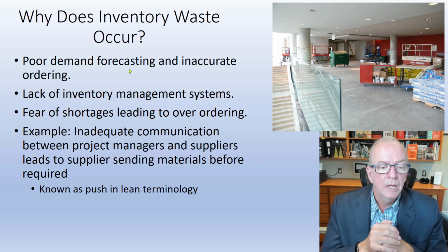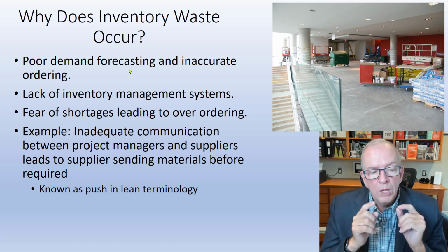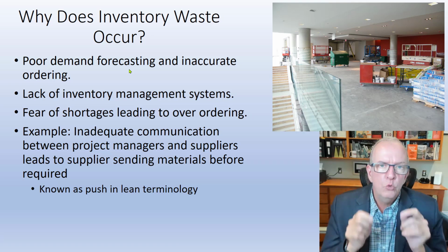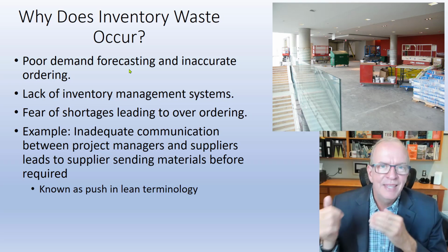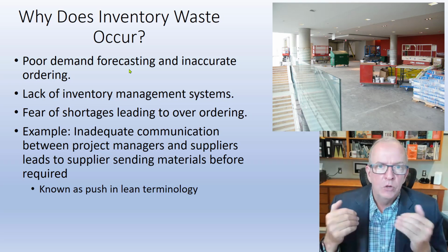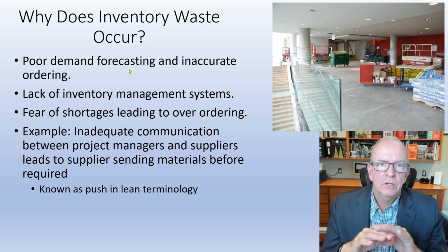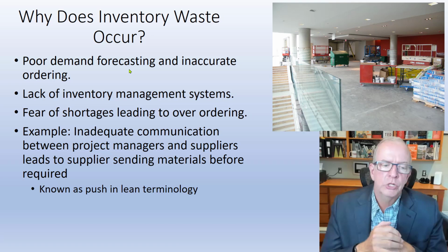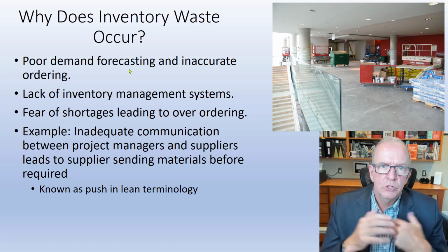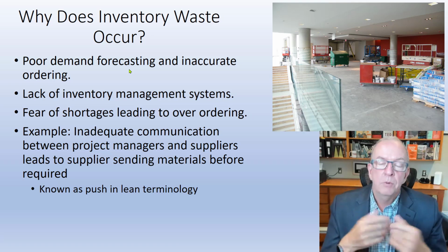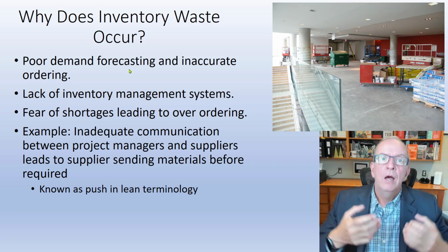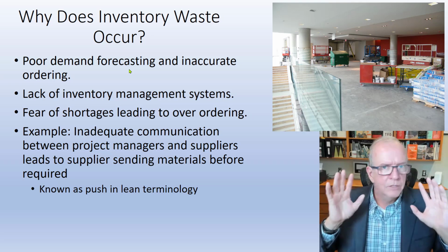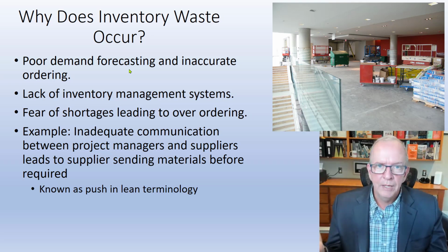But basically, if suppliers are pushing stuff to your site just because they have it ready and you're accepting it, then that's going to put you in a very reactive mode. We call this push in lean technology and terminology, as opposed to pulling it to the site as you need it. So big difference.